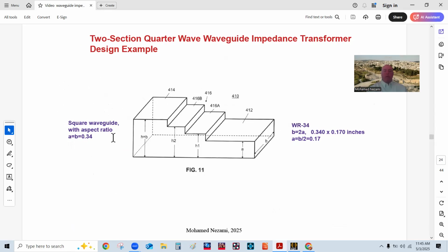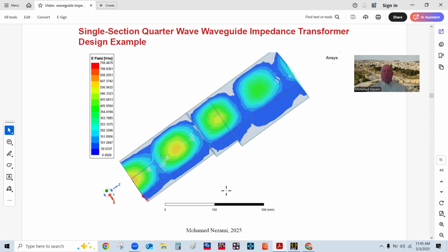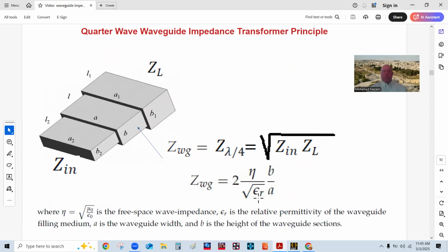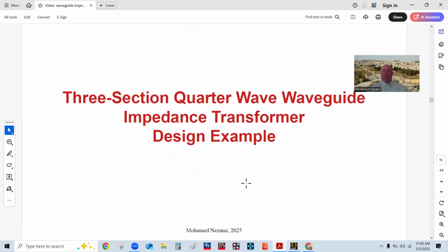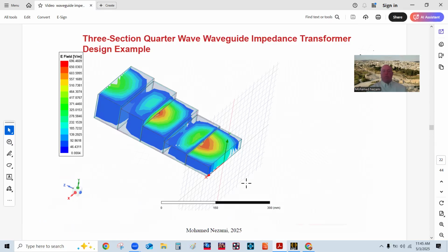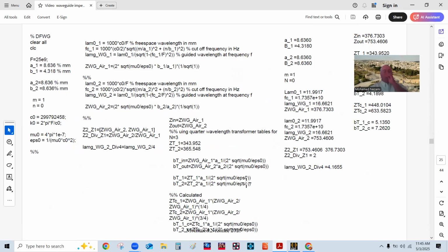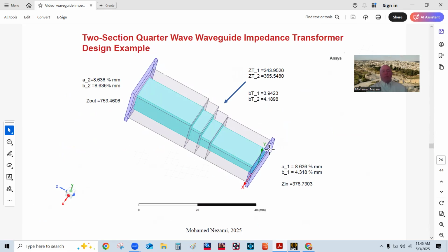And if you do that with a rectangular horn, a rectangular waveguide flared horn, the impedance is not as good as the square waveguide. Okay, the square waveguide, because if you look at the impedance on this equation, go back to this here. Now, this is for rectangular waveguide. B over A, if it was a square, this would disappear completely. So you've got this impedance in here, which is closer to the characteristic impedance of the free space. Okay, so you end up with a better return loss. And that's what I got basically.